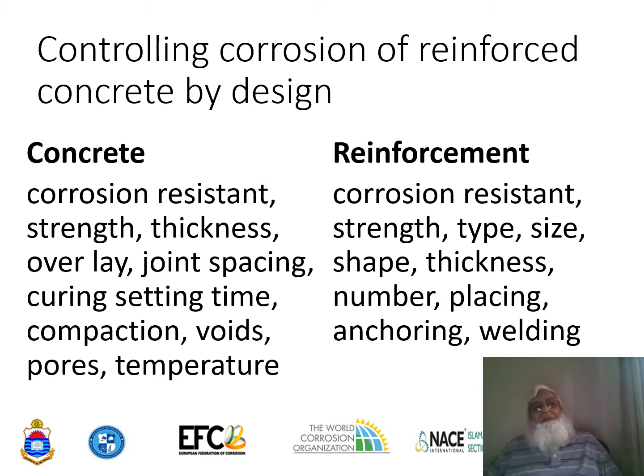And the overlay, which is normally put after the structure is completed, is made of a different material, not the same material as the Portland cement, and it prevents the corrodants from entering the concrete. Then joint space is another issue: during thermal expansion the concrete expands, and to prevent this we put in joints, which can absorb the concrete expansion force.